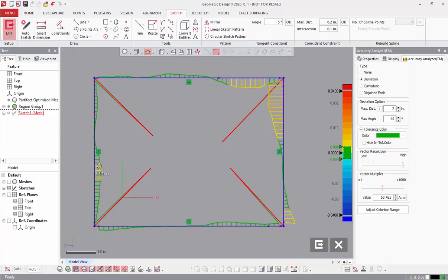3/4 thousandths of an inch of deviation in that area. The worst I think here is about 10 thou right up towards this corner, just under 10 thou. So that's at the maximum extent of the part, 0.53 inches in.